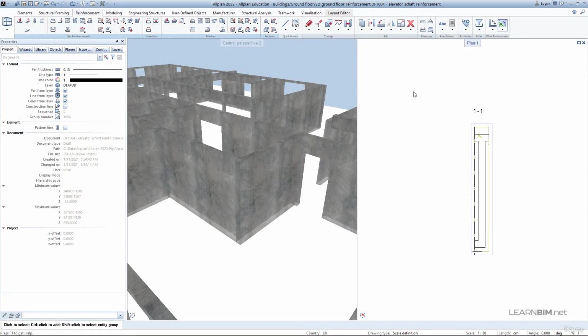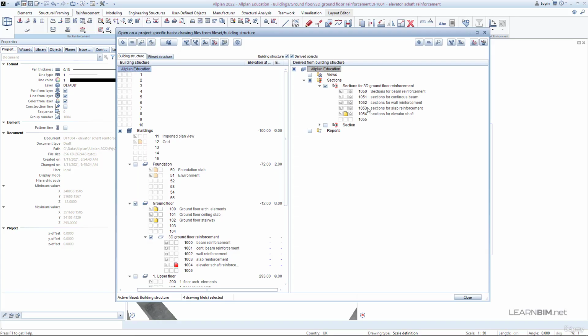In this video, you can learn how to quickly reinforce the elements using the Extrude Bars Along Path command. Section for one of the wall elements has already been prepared. For this way of reinforcing an element, only one section is needed, a horizontal section in this example. Have in mind that the section is in a separate drawing file and reinforcement will be placed in a new drawing